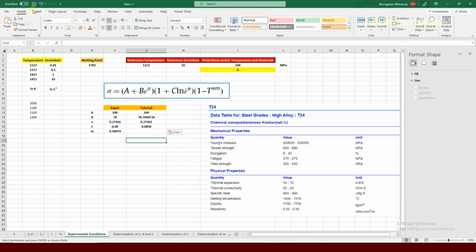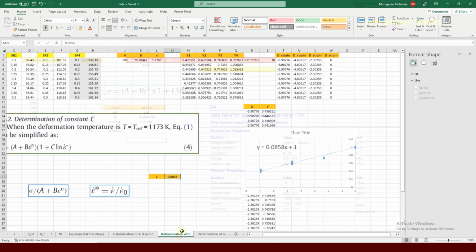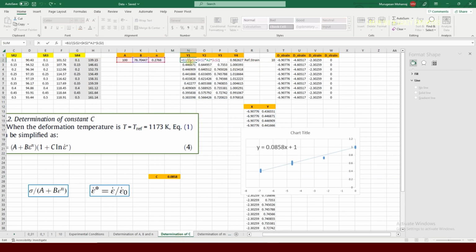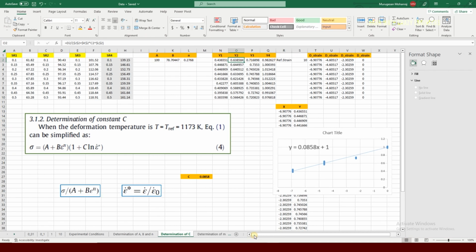It's similar. So the mistake I did was when I was calculating the left side parenthesis, the strain value kept on changing. It was A2. Then in this case, it was supposed to be C2, but it was B2. So when you are making this calculation, make sure that instead of putting data like this, just remove this column and delete it and then keep only 4 columns.